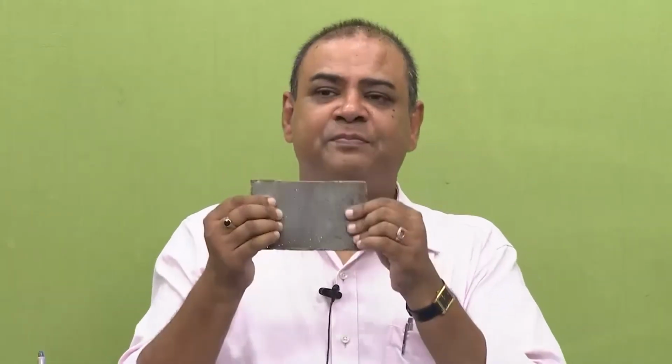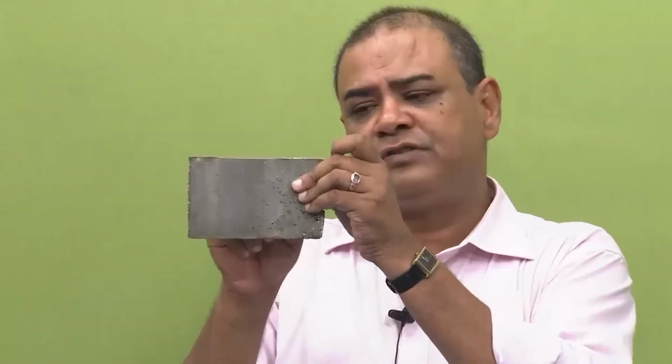That is why pitting corrosion is so dangerous: it will not give you any signal before a fracture happens. Though we are able to see these big holes, sometimes these holes are so microscopic that unless you go under the microscope you will not be able to see them, but actually it has punctured and reduced the cross section thickness. So, this is a severe mode of corrosion when we talk about 8 forms of corrosion.